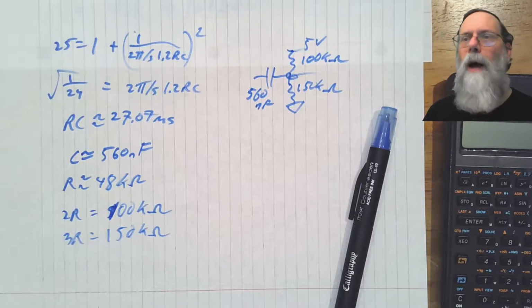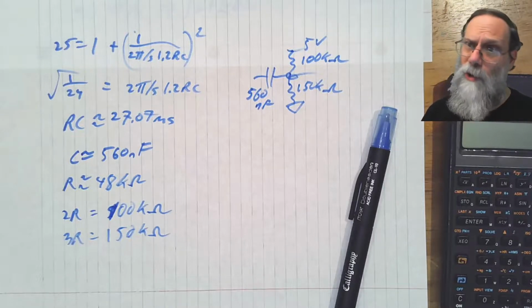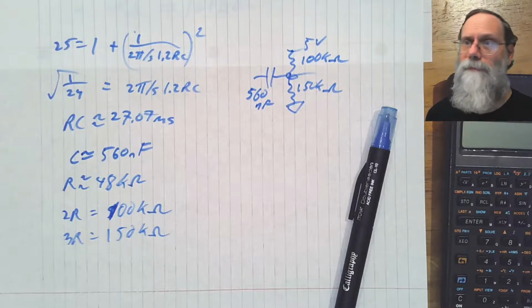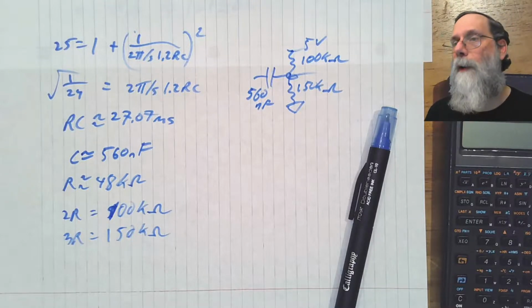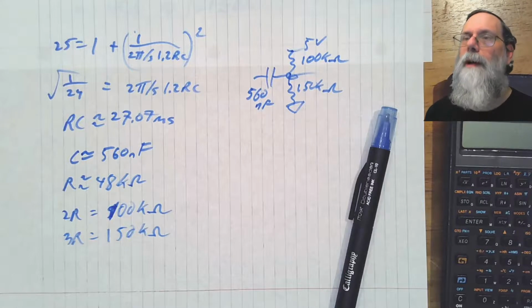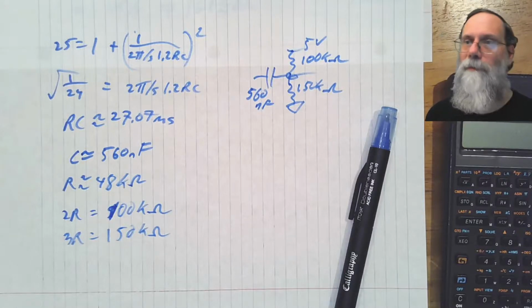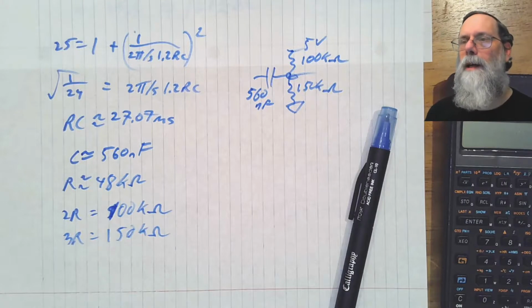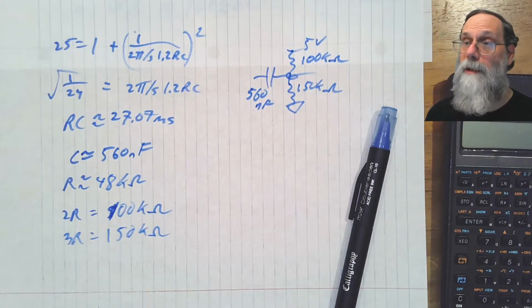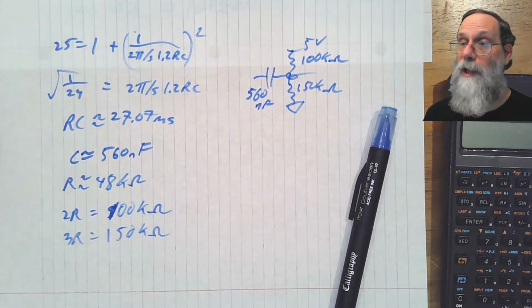Or somebody will say, I want you to reduce 60 hertz by a factor of 10 or 20. And then you're far enough out on the curve that you can use these straight line approximations that we have. The filter's just behaving like a resistor or just behaving like a capacitor. This is about as complicated an example as you're likely to encounter for this sort of recentering exercise.